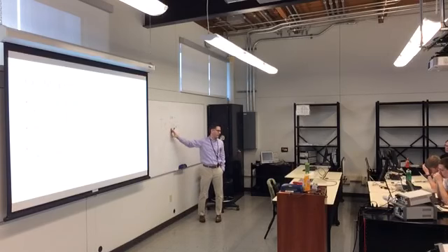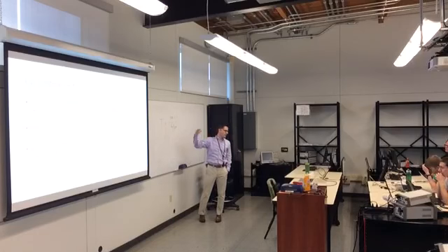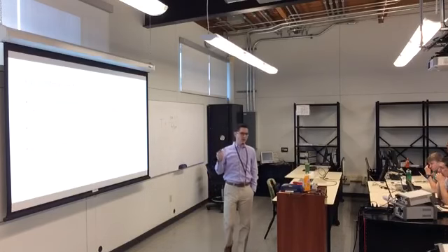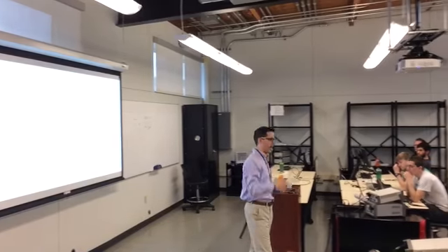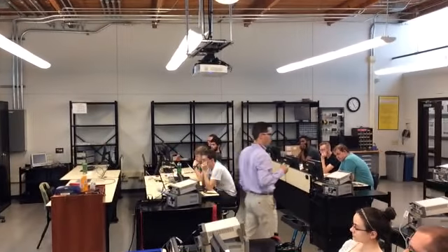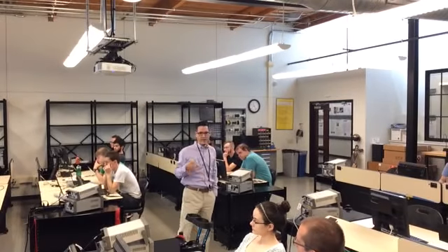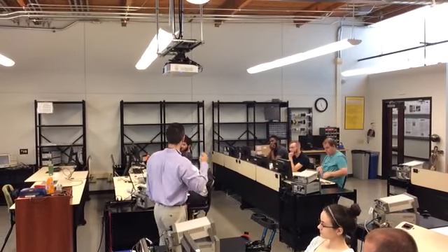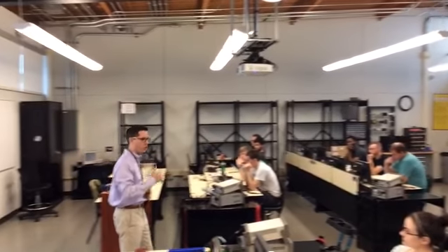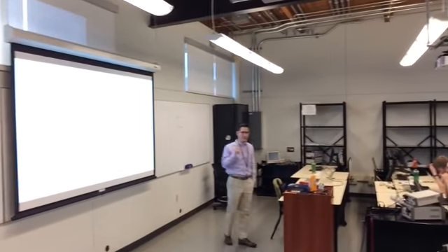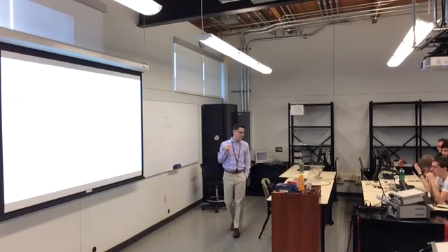Let's say you scale the clock by 16. You've now cut down the clock speed by 16. If you slow down the clock, that means you can count for a longer amount of time. You've only got 2 to the 16, you've only got 16 bits, and if you're banging away at them fast, you're going to count a small amount of time. If you slow down the clock, then you will count for a longer amount of time. Bill, you look confused.